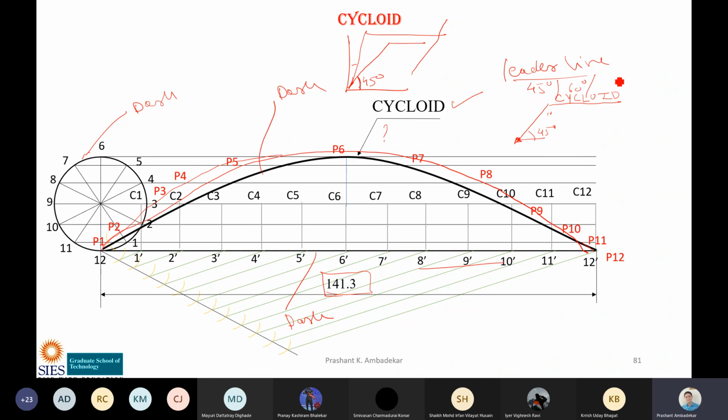So this line is called a leader line. It is used to show notes or marks, or to write dimensions. Sometimes you have to write a dimension, like for this circle. So what will you do? Like this, and phi, I don't remember the diameter, I am just writing for understanding purposes, 535. So this is the dimension. What does this phi indicate? Phi indicates diameter. Another thing: this circle, either you can dimension it like this or you can dimension it like this. Take it here.